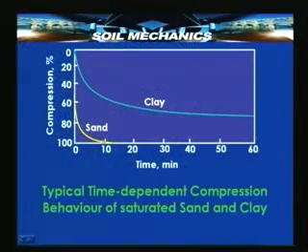If you take a small sample of a clay soil, let us say in the laboratory, and subject it to a load and measure the compression that it undergoes and plot a graph of the compression versus time under a certain load, you will find that the clay soil goes on showing an increasing compression in terms of percentage until it reaches asymptotically a large but steady value beyond a large duration of time, whereas sand shows a quick increase in compression within a very short duration of time.